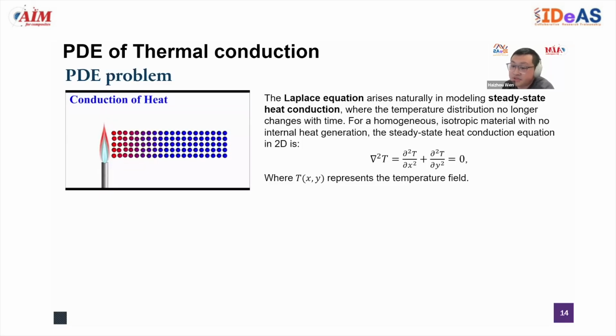in mechanics. So those 3 equations are the mass equation, the momentum or NS equation, and the energy equation. They represent and originate from the 3 basic principles of physics, which are conservation of mass, conservation of momentum, and conservation of energy. So the Laplace equation here of the temperature is a simple variant of the energy equation. The equation only considers a temperature change along the spatial dimensions and no changes on the time axis. Therefore, this is a very canonical equation that studies the steady state.